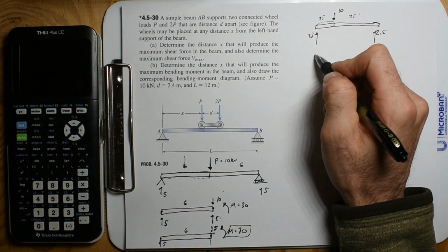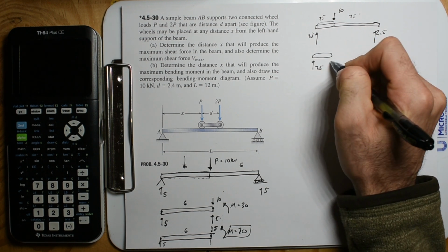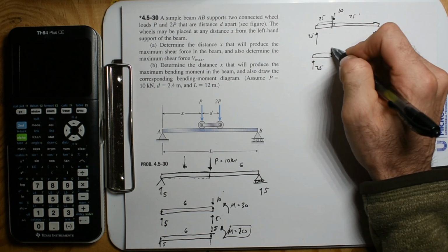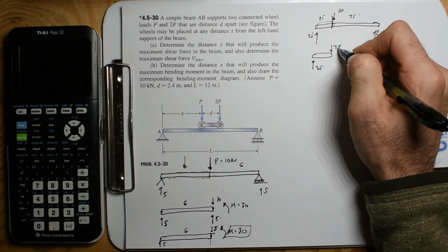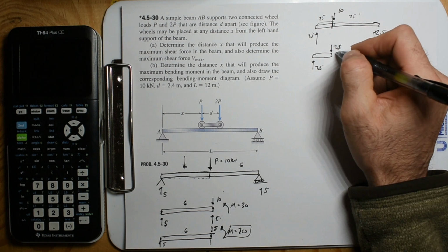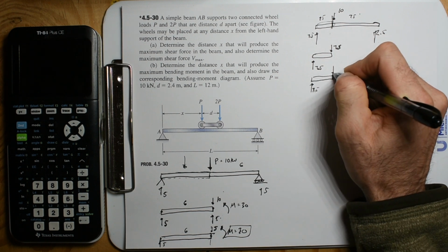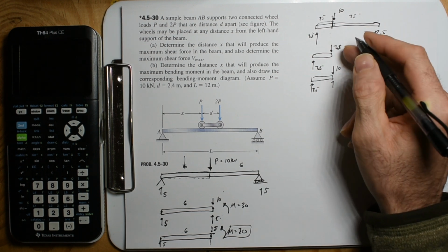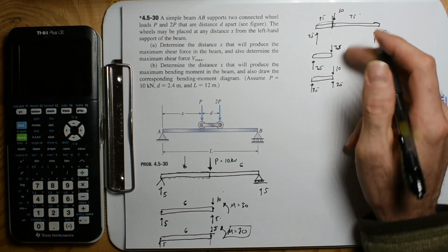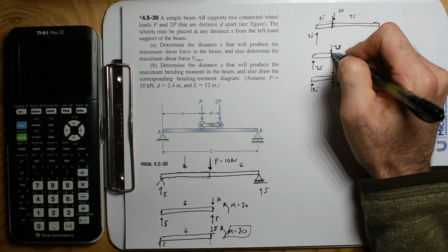So now let's chop this. Let's chop it right there, and so we're going to have 7.5, and we'll just chop it right in front. That's kind of an interesting thing to do. So we're going to have 7.5 kilonewtons down. Okay, so in that case, we're going to have a shear force of 7.5 kilonewtons down. Now let's actually chop it where we have 7.5, and then we'll have 10 kilonewtons. So this way, right over that load, we would have 2.5 kilonewtons. That's going to be our shear. So it's kind of interesting. We're going to have the biggest shear right in front of that load.